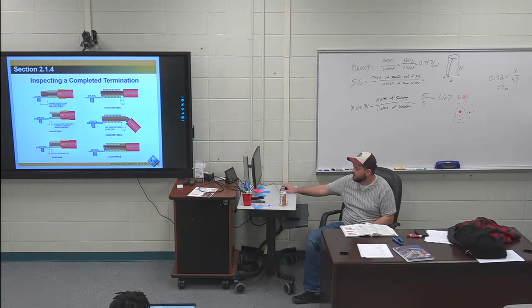All I do is stick enough copper through here to where I can barely see the copper, and that's where I make my crimp. You also never want copper more than a 1/16 of an inch outside of here. Usually they give you a little bit of playroom right here, but don't strip 2 inches of insulation off of this thing, throw it in there and crimp it. Like that's not gonna work.